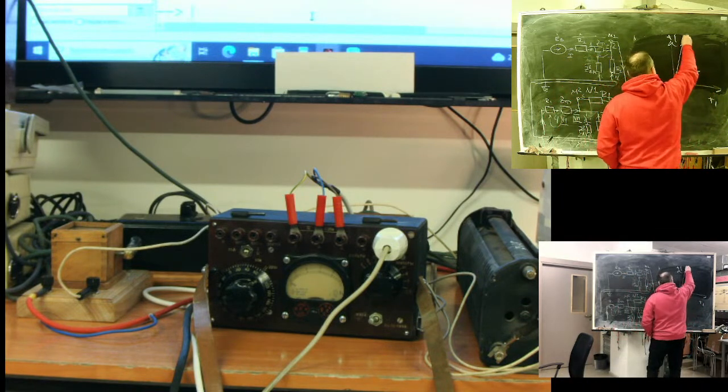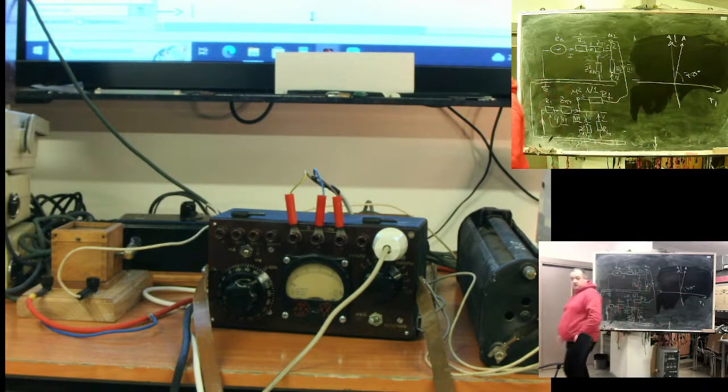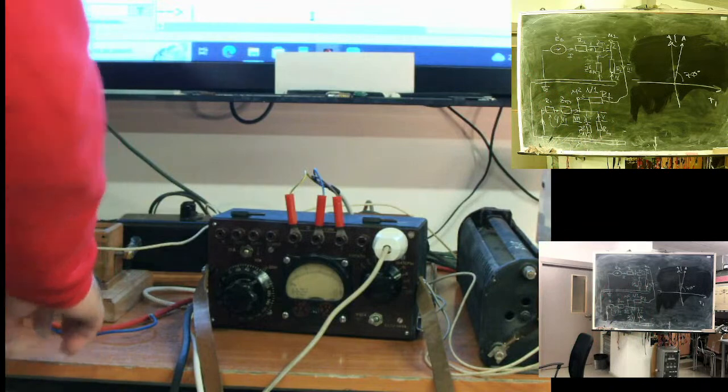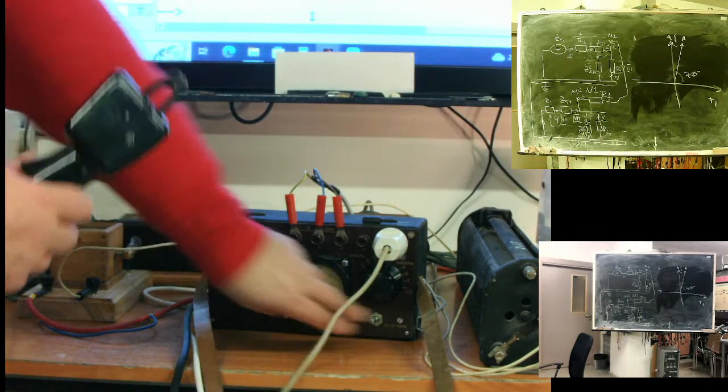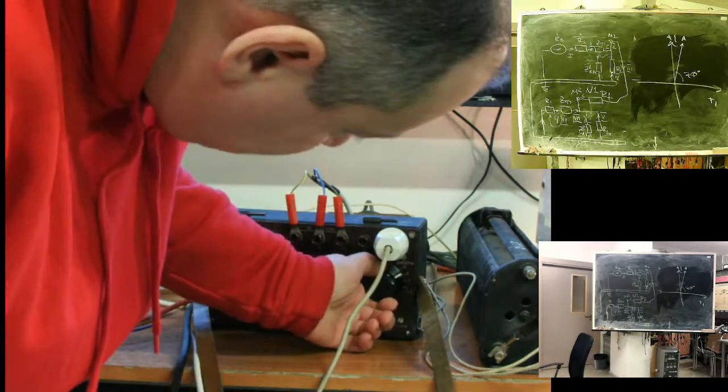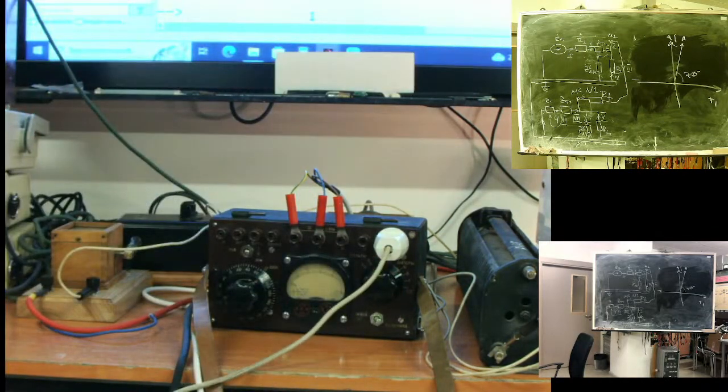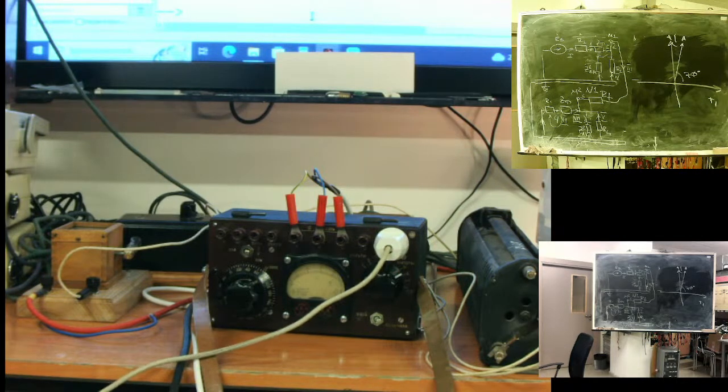Plausible for A phase. Yeah. Let's check phase B. For phase B, 7.5 in theory. I will switch for 10 amps. Here is my B phase, and it falls like this.